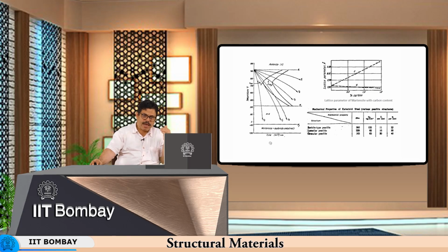But then as it starts doing its job of road rolling, it undergoes a very severe amount of strain, severe working by the sheer weight of the road roller itself and the hardness of the surface it rolls on. So progressively it gets hardened. With additional work, the road roller rim tends to get hardened.